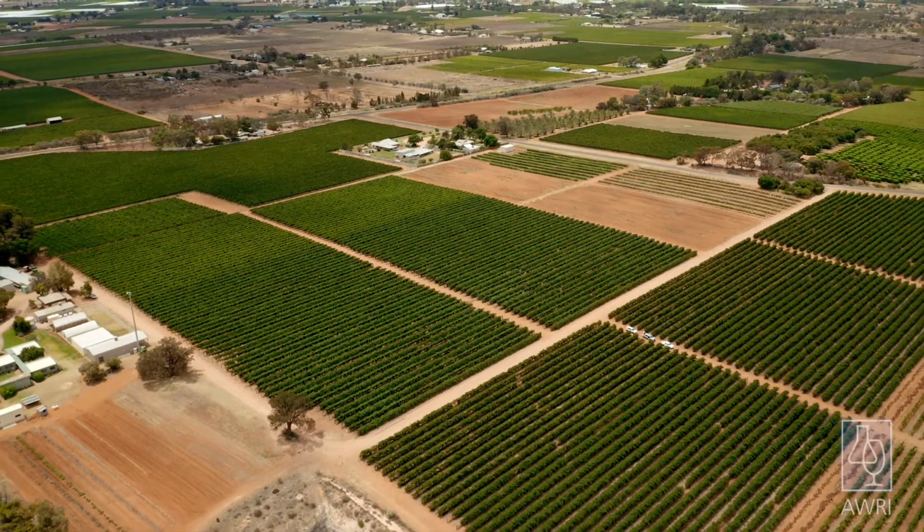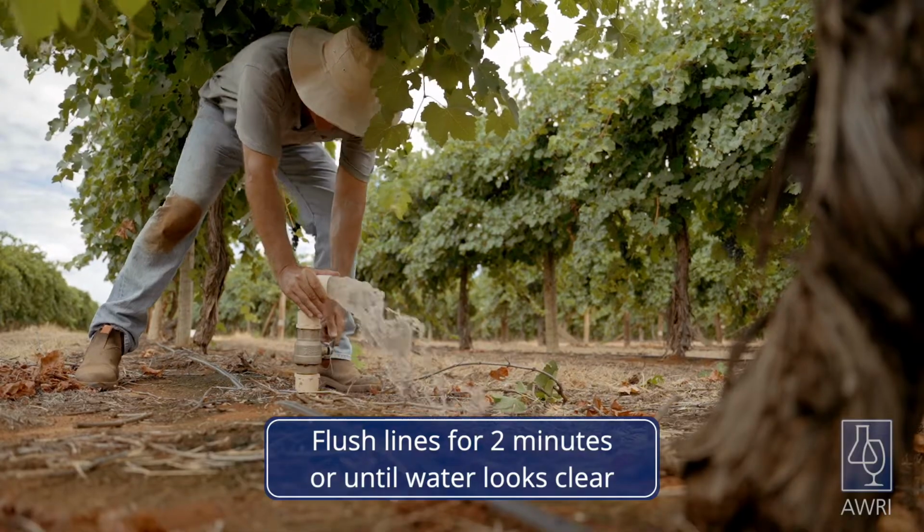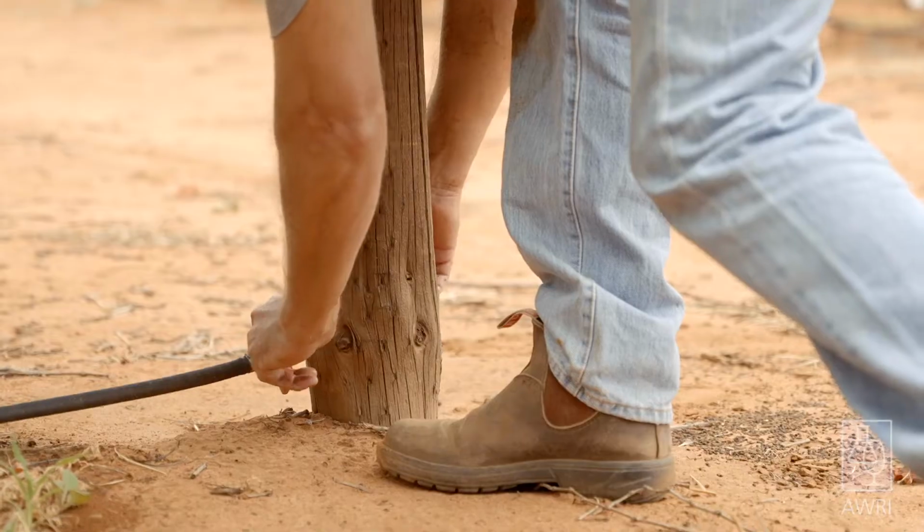To flush the main line, open the valve and flush for 2 minutes or until the water runs clear. To flush the sub-main, also flush for 2 minutes or until water is clear.